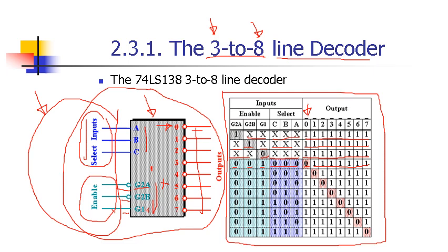If you have more than one memory chip, up to 8 memory chips, you can activate the first memory chip, the 0 memory chip, by providing 000 at the select lines, and you take your chip select signal from the first output line of your decoder.